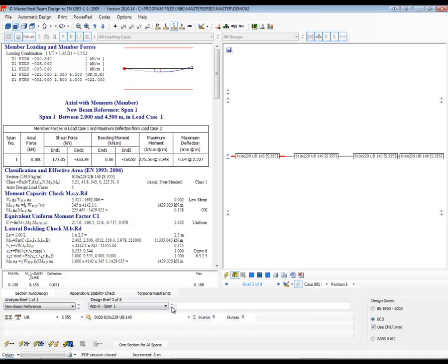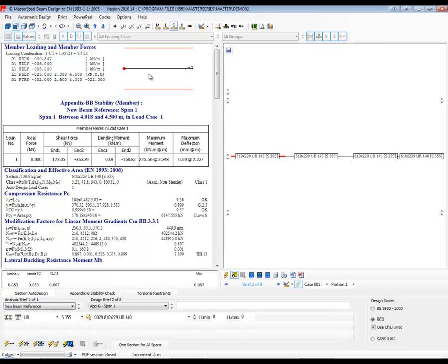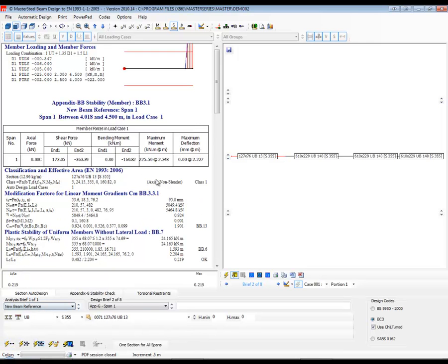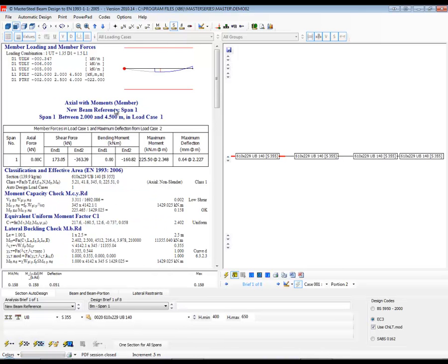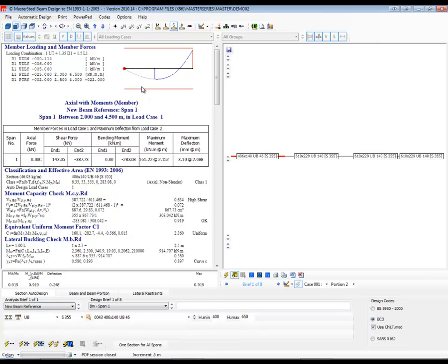We have our first span, we have any Appendix G loads in that first span, and you'll notice obviously that we can really redesign that coming down, coming back in the first span. If we resize that, auto design that, we can see that we can get a lighter beam because it's continuous. We're now down to 46 kilograms. Wow, that's a big difference.